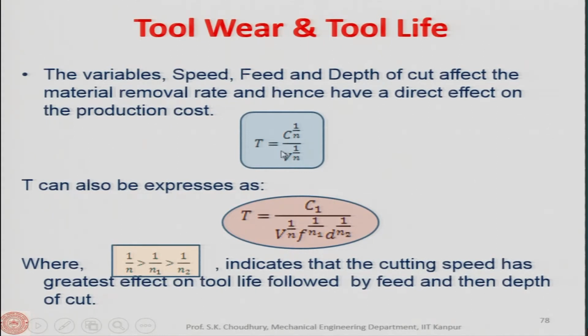So the tool life has to consider these factors, because as you increase the speed, the tool life decreases, because the tool wears out faster. Similarly, as you increase the feed, the load on the tool will increase, and so with the depth of cut.